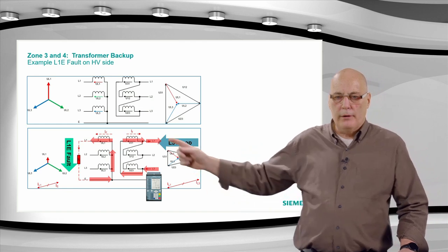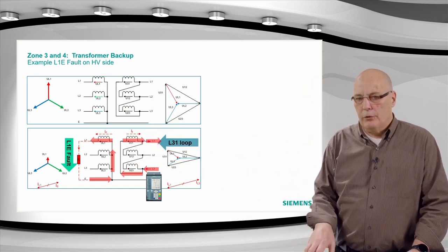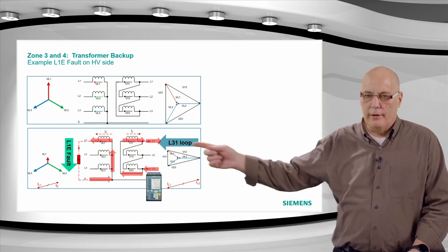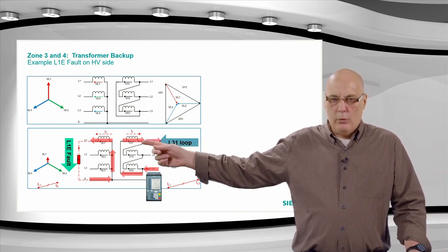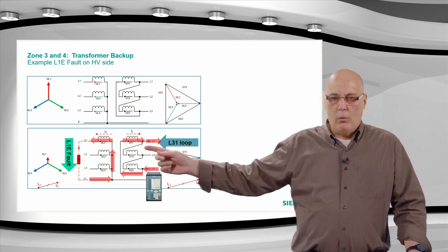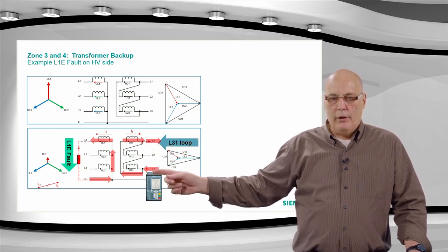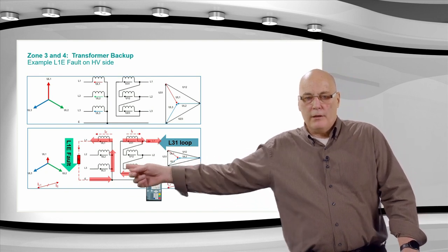That is the loop on the HV side. Then due to the transformer coupling, that couples onto the delta side, and you can see there's current in this limb, so we will have current flowing out here on L1, and the current is flowing in here on L2, but it cannot flow through that limb because there's no current on the other side.